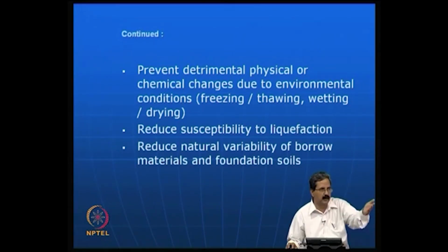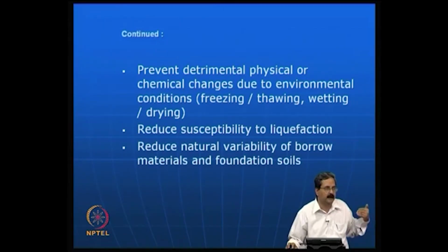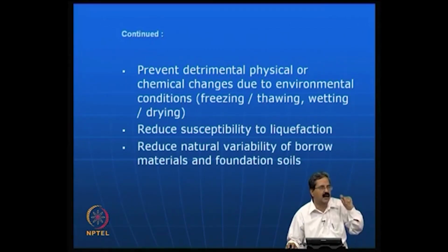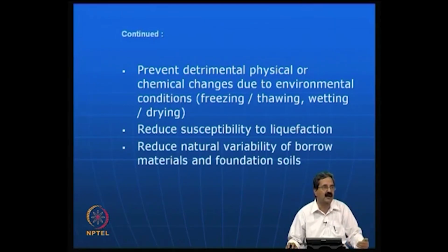Maybe in the next area there is another borrow pit material, a different soil at the next site, and then the foundation of the big structure is lying on this soil and then that soil. The way it should be done is that you should calculate the stress-strain response of both materials and compare whether the materials have the same stiffness. These are two foundation soils, one is here, the other is there.